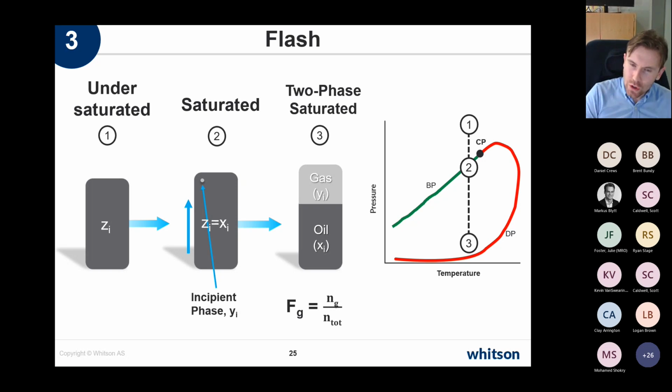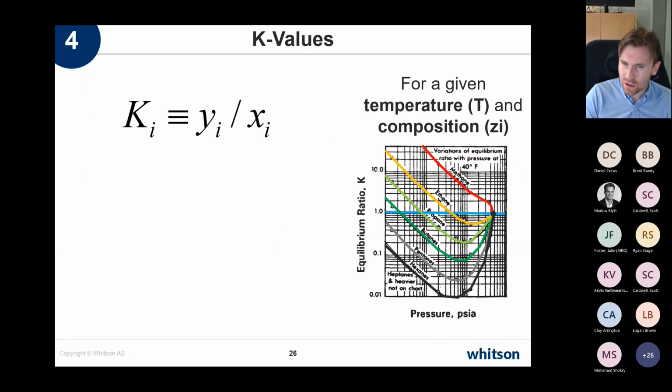Very, very relevant for this, and this is a little bit important, and it's a little bit also undereducated in university. But this, according to Curtis, is one of the things that you should know about if you do PVT in the oil and gas space, because it's what you need to understand complex PVT behavior. For instance, multi-contact miscibility, and also, for instance, retrograde condensation, and that's K values. And K values is essentially what an equation of state generates for a given composition. And once you have the K values, you can then determine the amount of the different phases.